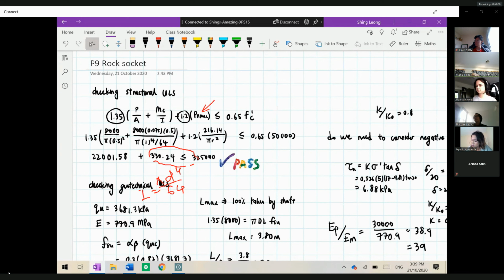Start with a known diameter and see whether the right and left sides are satisfied. If it is satisfying, you don't need to refine in the exam environment. But in the design environment, obviously it is good to refine it. In the exam, if it is satisfying and there is still a big margin, you carry on. Make sense? Got it.